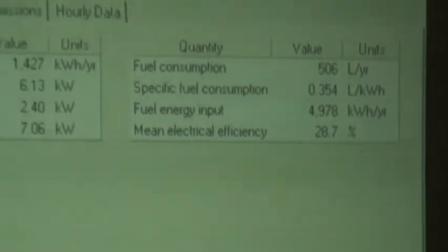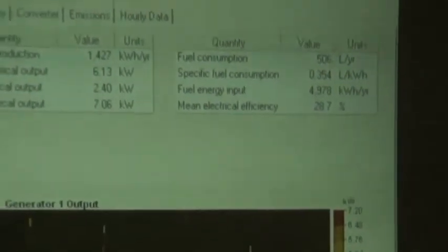Yeah, one of the things we discussed in quite some detail today, one of the core components especially from a site maintenance point of view, is what we see as a common practice in Africa: people bringing a lot of fuel in one go and not going to site for 2 weeks, and then again bringing a few hundred liters of fuel. What we see in some places where diesel theft is quite significant, like India, Indonesia and Pakistan, is that they have started going to the site infrequently and putting in less fuel instead of bringing more fuel in one go.